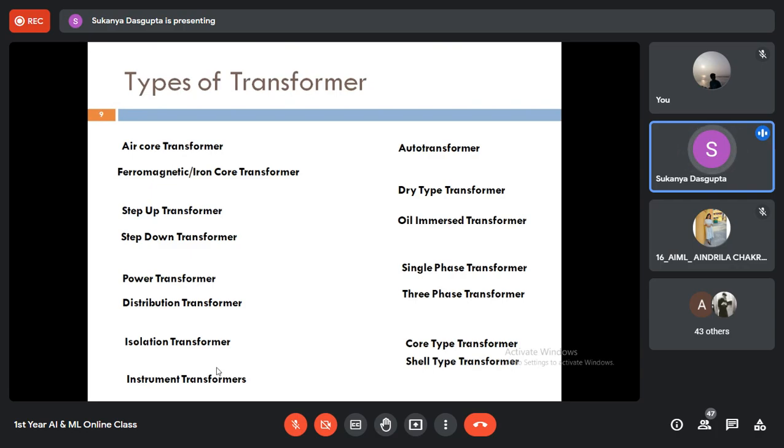They can be used in the switchgear because they can be used as a measurement device and a protective device as well. CTs and PTs are used in power system applications to protect other switchgear components like relays, circuit breakers, etc. So they are mainly used as protective devices. They can also be used for the protection of transformers, bus bars, and generators used in different switchgear applications, and also they can be used as measuring instruments.